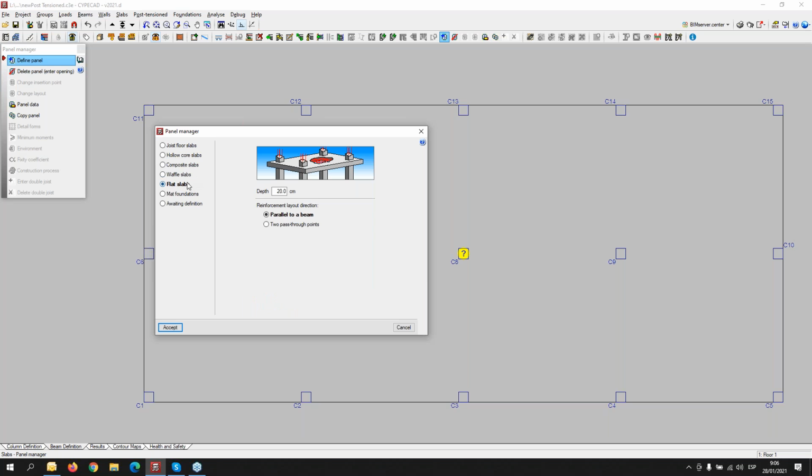The next kind of slab is the most simple one, the flat slab. We need only to define the depth, and we will have reinforced bar in two perpendicular directions. We have the mat foundation too, and here the user needs to define the depth, the soil resistance and the subgrade modulus in order to obtain the matricial model.